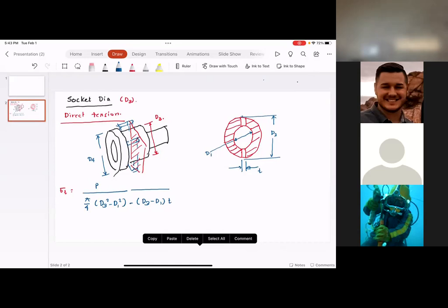It's not possible to do those types of detailed analysis for a three-dimensional structure by hand. So you would follow these basic guidelines, come up with some basic dimensions, select the catalog item, and perform the finite element analysis inside the software.